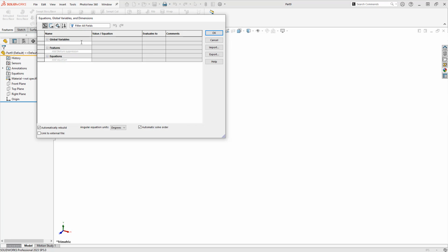I think global variables are a great modeling approach, especially if you're preparing for things like the Certified Solidworks Professional or Expert exams. You get a design or a drawing and you have dimensions listed as A, B, and C. Putting those in as global variables and changing them here and updating an entire part is the way in which you are more efficient on those types of modeling tasks.